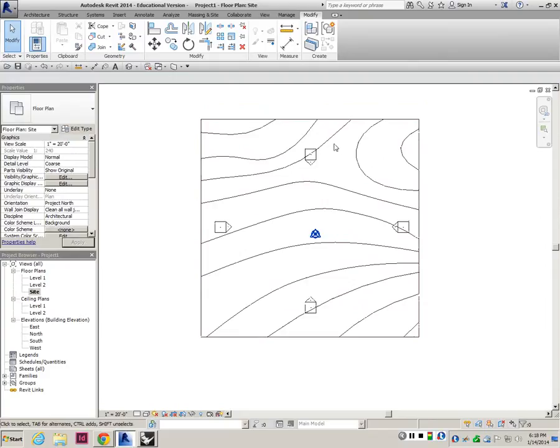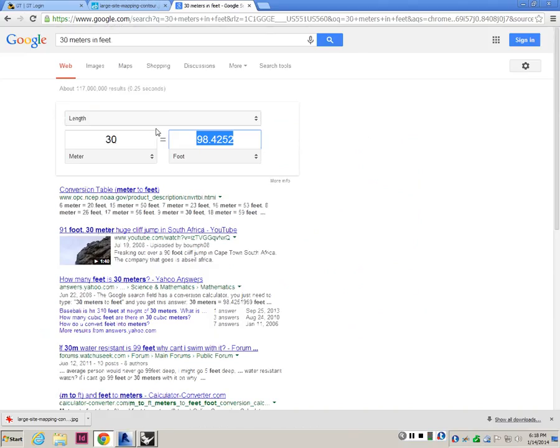Now I don't know about the slope yet, but since this is 200 feet, let's think about some sort of percentage. If you want to create, let's say, 15% or 20% of slope, then in 200 feet we would have to climb, I think, 1/5, 40 feet, right?